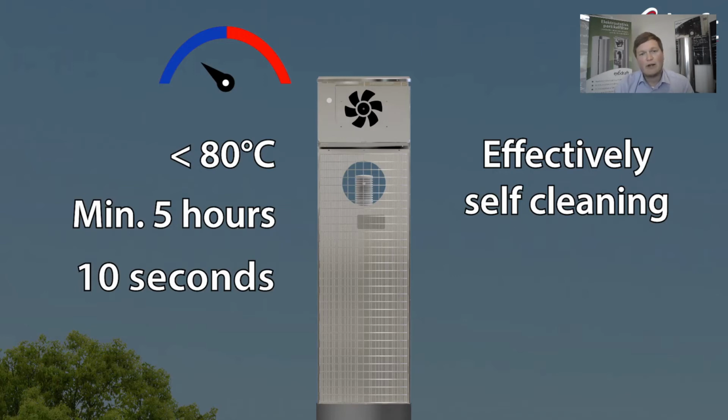So when the fire has burned out, the filter actually will deactivate itself, and before it's going into the standby mode again, or the idle mode, the filter will run a self-cleaning cycle. This is only done if the filter has been running for more than 5 hours since the last cleaning cycle. And once the cycle is activated, it will run for about 5 to 10 seconds. And there are two ways the particle filter will deal with the particles.